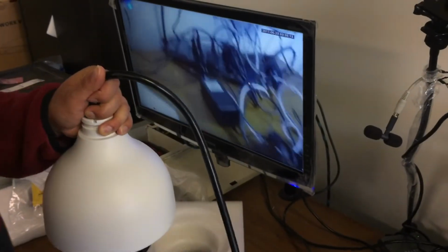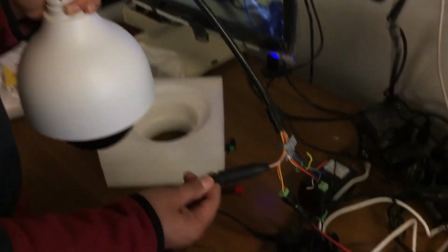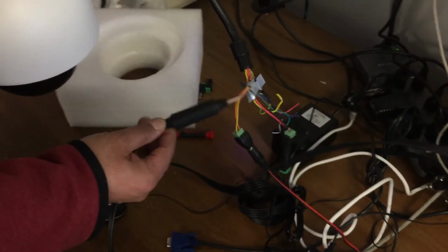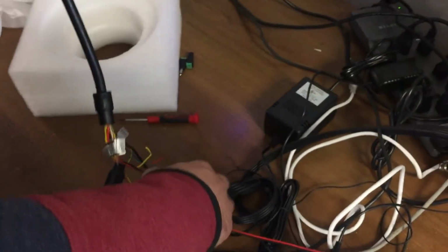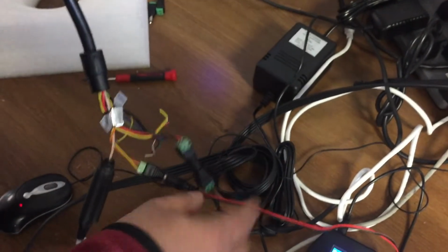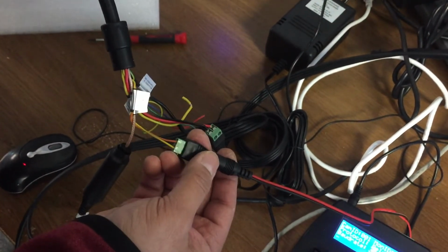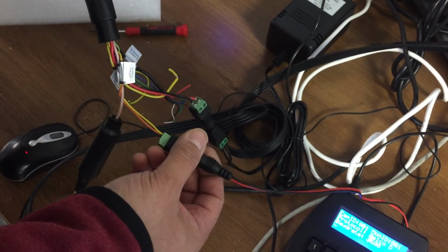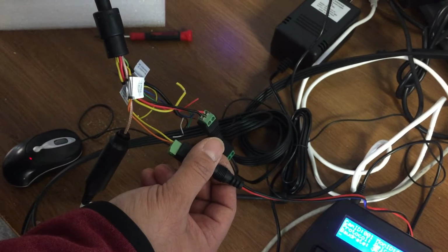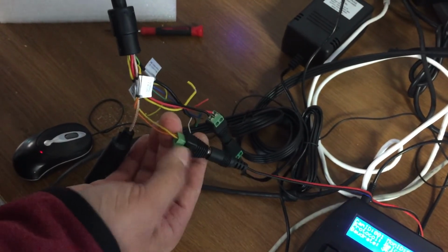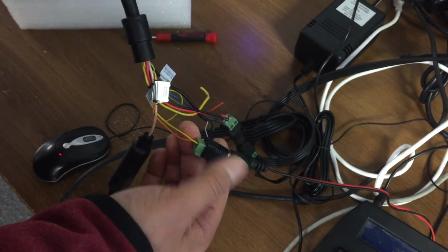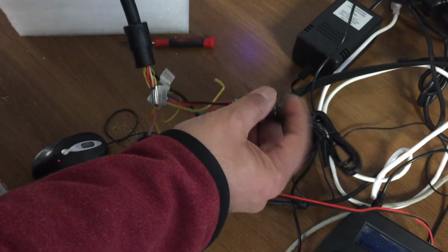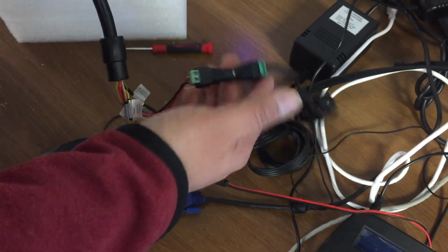And the way it's connected here on the pigtail, let's take a look. You've got a BNC for video. You've got power, 24 volts, the red and black wire. And the yellow and orange are your RS-485. Yellow is positive, orange is negative. It's imperative you get that correctly. You will not see a green and black tip on the one when you receive it, because that's only something we use for testing. But we will include it here for the power to make it easier for you.